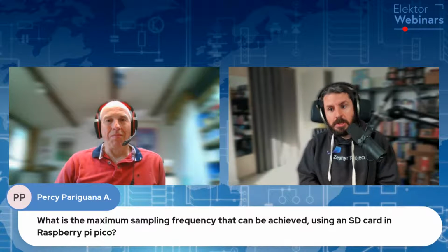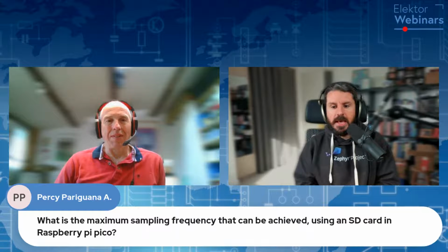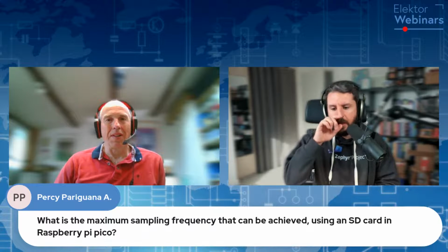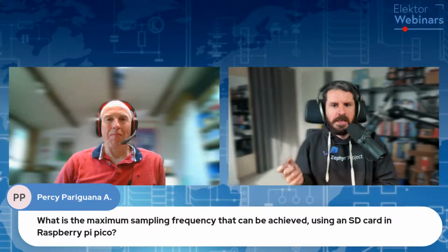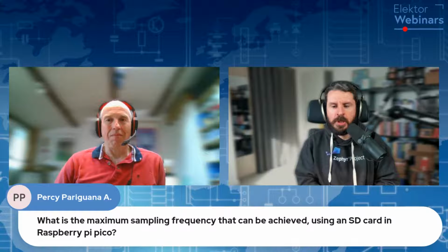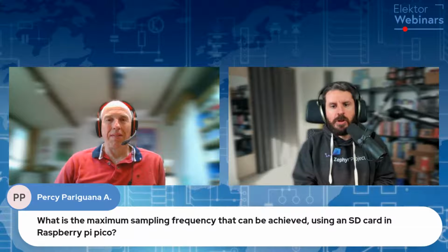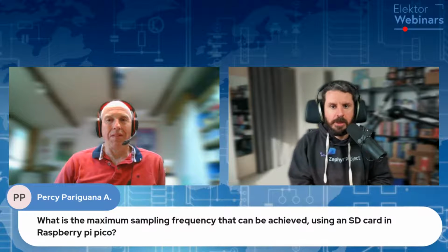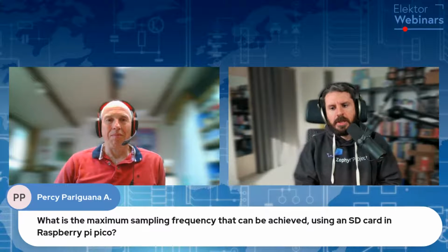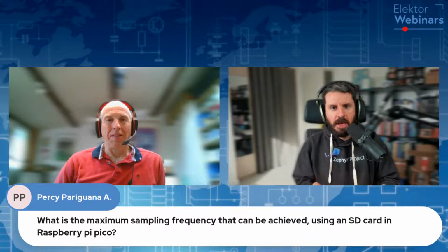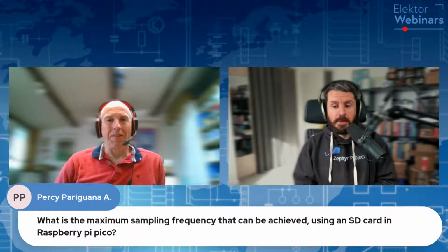Another aspect to the question, specifically around Raspberry Pi Pico, is that some of you might be familiar with the PIO in Raspberry Pi Pico, the ability to use a small assembly-like language to create your own driver that manipulates all the pins at a really, really low level. That way you can have really big and really fast sampling rates. I think there is actually a driver in Zephyr that uses PIO to drive RGB LEDs, where the timing is usually really tight. It does it that way.